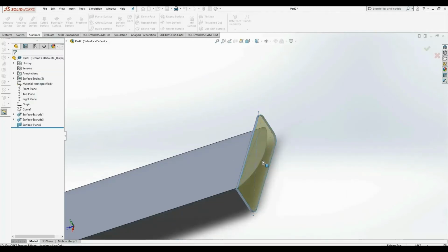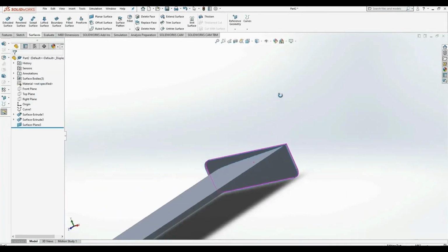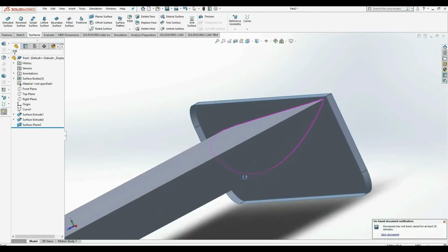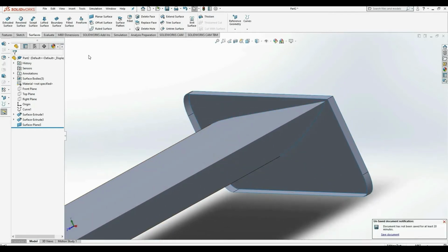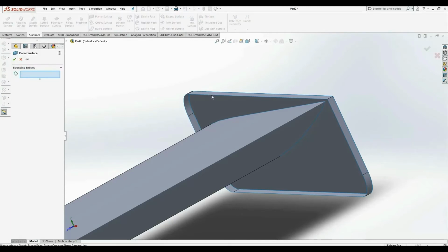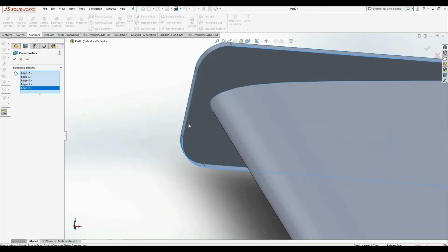So the end plate is now capped, the inside is not, so we just need to make sure that we then do the same again. Now you might be thinking here, we need to make sure that the end plate also doesn't cover the inside of the aerofoil shape, because that will give the same fault as I just mentioned before in terms of not giving us a consistent surface to then stitch and create solid.